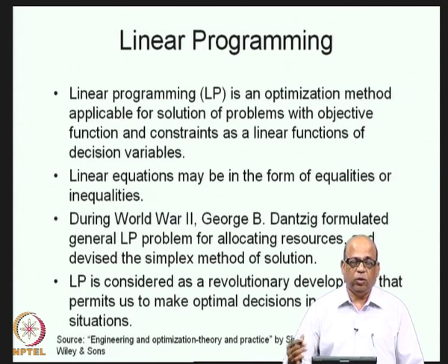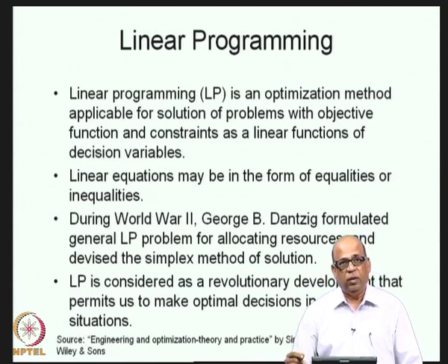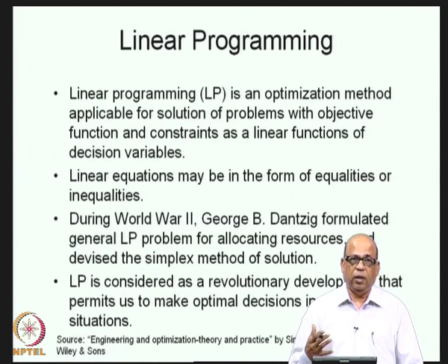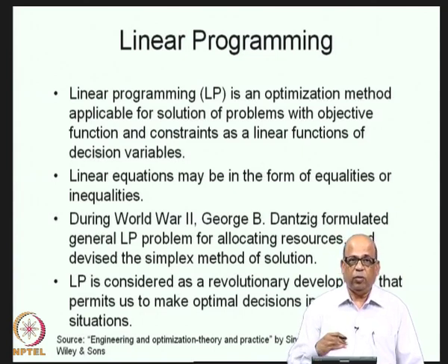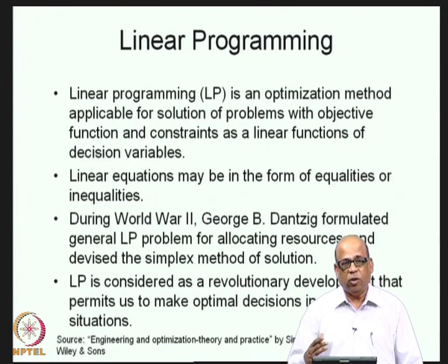And as you will see in the applications lectures, where we deal with large scale water resource systems problems, LP becomes a very handy and elegant tool for screening of alternatives, for obtaining optimal reservoir operating policies, for obtaining optimal hydropower generation, obtaining optimal flood control and so on. So, when we are dealing with large scale optimization problems, linear programming, mainly because of the simplex, revised simplex and the Kuhn-Tucker algorithm, becomes an extremely handy tool for systems analysis.